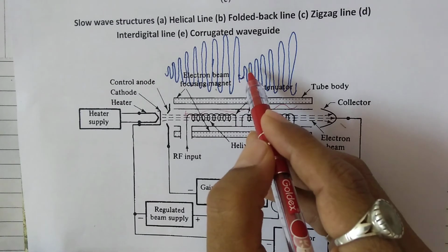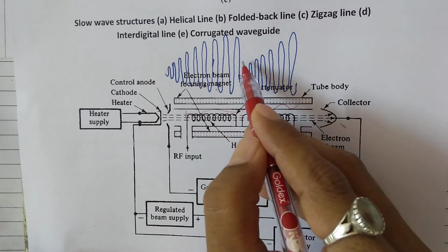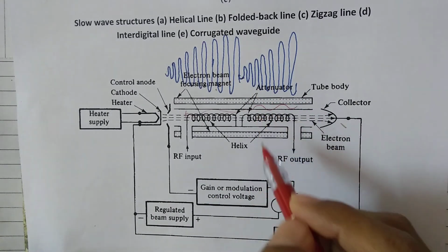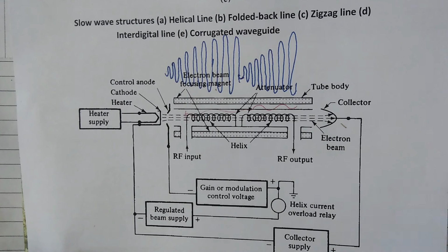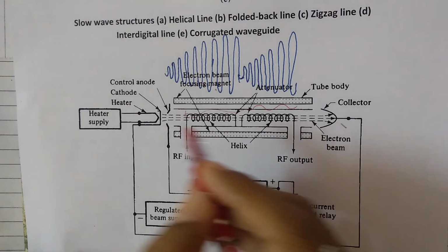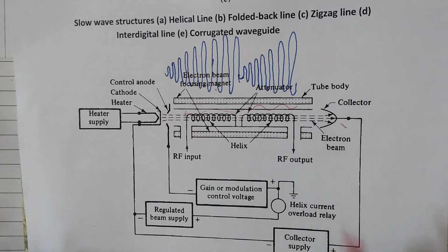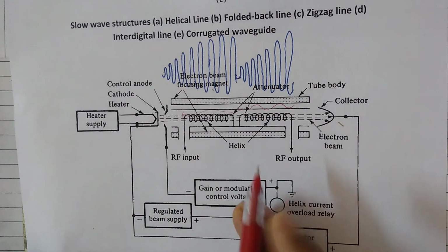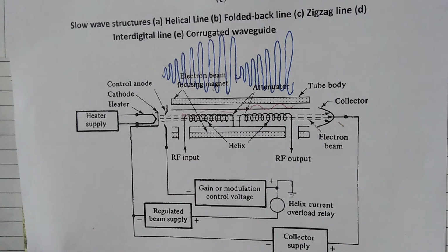No doubt it is going to reduce the signal strength by a certain amount, but they are protecting this amplifier to keep it acting as an amplifier, and if any reflections reach the source, that amplifier may result in oscillations because the stability of that circuit would be disturbed. So that way these attenuators are placed.